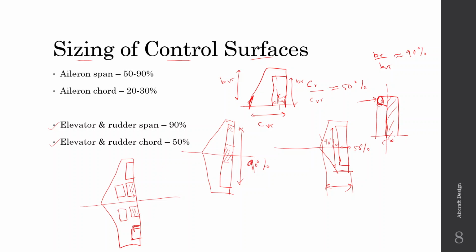So the spoilers may be used for this. Another advantage is that the spoilers may also be used for rolling the aircraft in addition to the ailerons. At high speed, just using ailerons may cause something called adverse roll. In this situation, the aileron deflection bends the wing, and this bending of the wing causes a roll which is in the opposite direction than the intended roll.